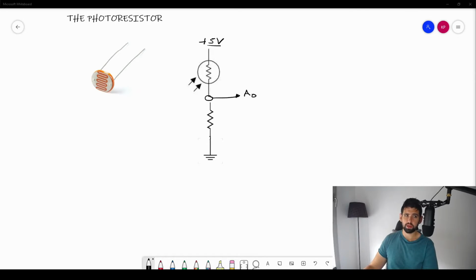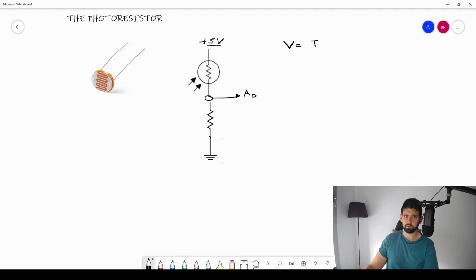So Ohm's law, just to recap, is that my voltage is equal to my current times my resistance. We're going to use this to calculate what happens when my resistance increases and decreases with our photoresistor. So for the circuit, as you'll see later on when we build it, this resistor here is constant. Let's say this resistor is 5 ohms. In the tutorial, it will be 10,000 ohms, but just for calculations, I'll show you guys 5 ohms. Now this photoresistor can increase or decrease depending on the light source. Let's assume when there is no light in your room, it might be 5 ohms as well.